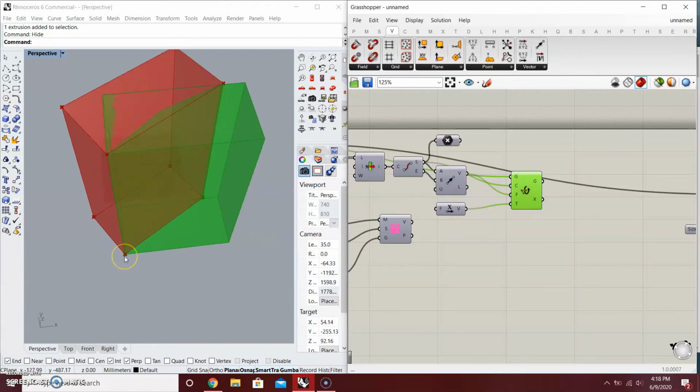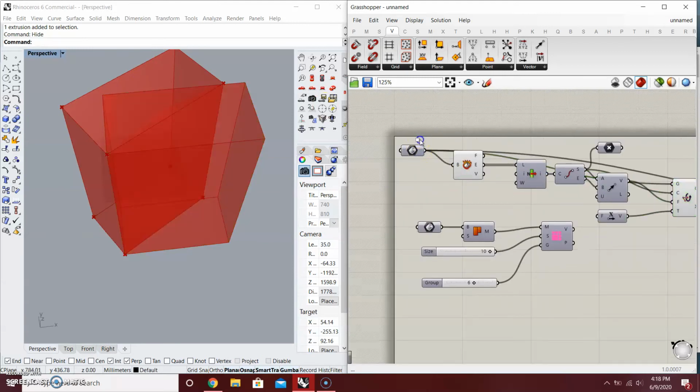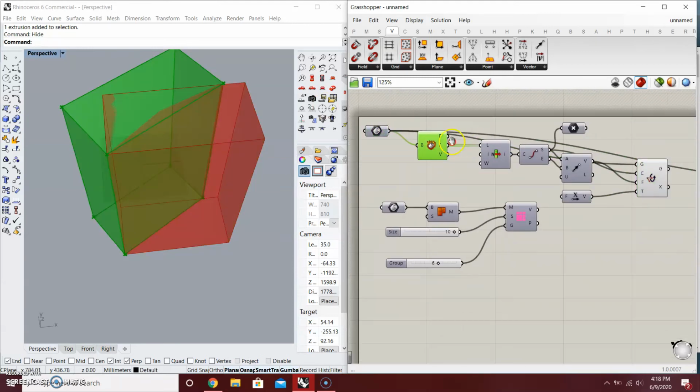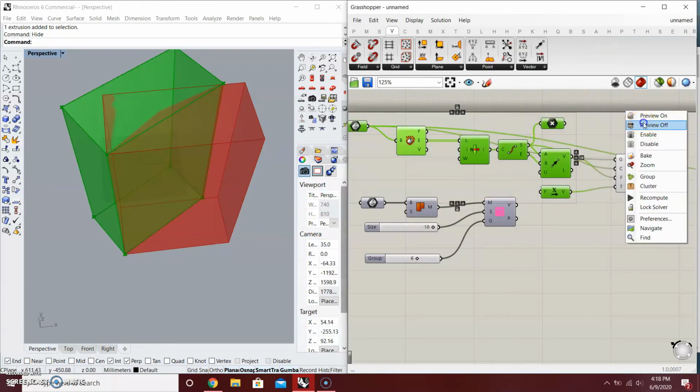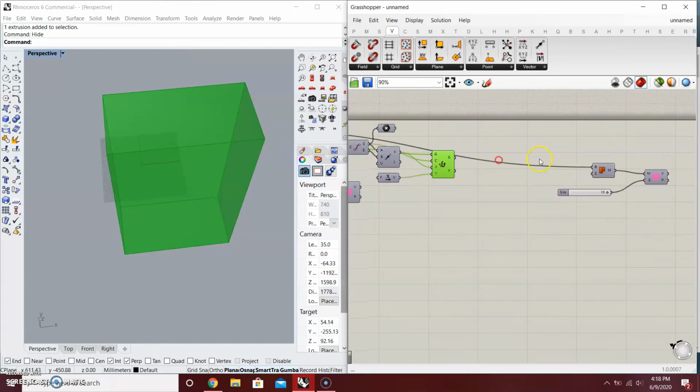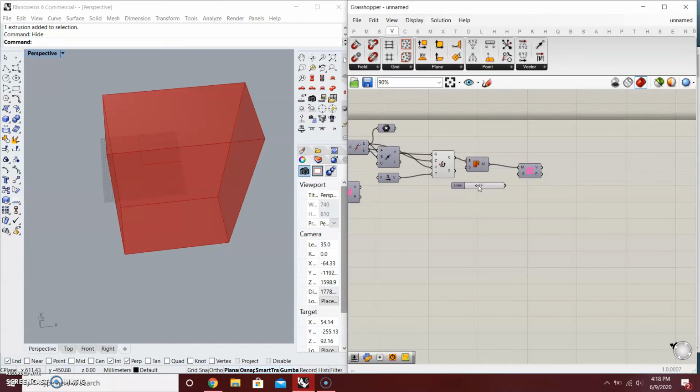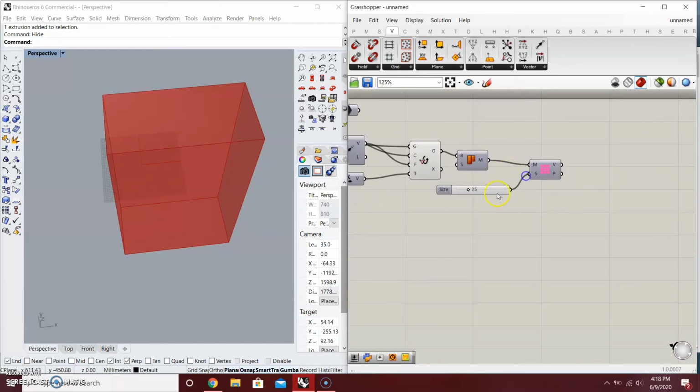You have successfully rotated this thing here into that, because that vector is the initial one here, and that X vector here is the resulting one. So we want to hide that. And starting from here, you can actually voxelize it. Make this one bigger, just to make Grasshopper lighter.